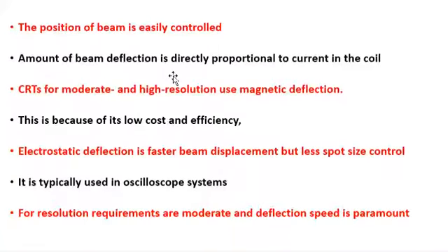The amount of deflection created for the beam is directly proportional to the amount of current in the coil. And the more current we consume, definitely the more the quality of the system deteriorates. So in this case, you have to strike a balance, increasing the current to the minimum in such a way that it will not cause degradation of the system.